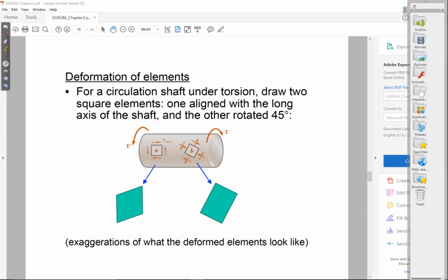That's because steel is very strong in tension. So if you take a shaft that's very brittle, and you twist on it, here is something that we know. The ultimate stress in torsion of something that's very brittle is greater than the ultimate strength of that material in tension.